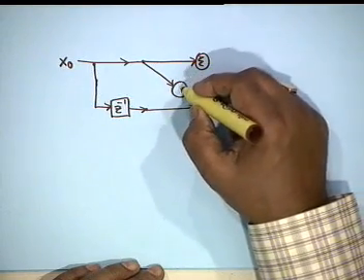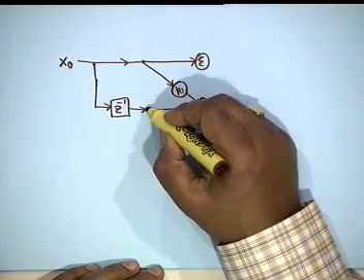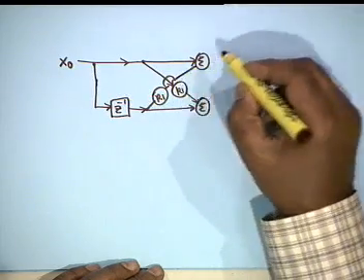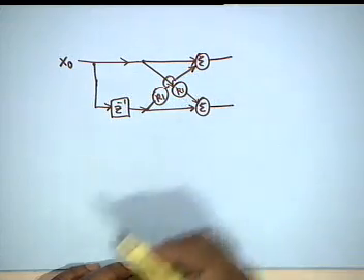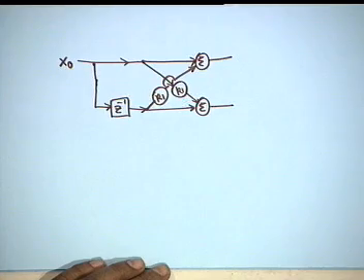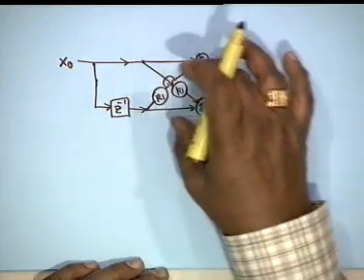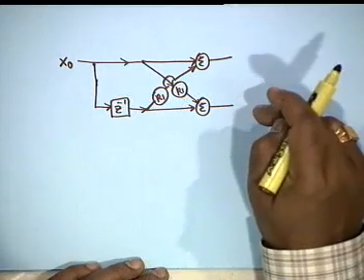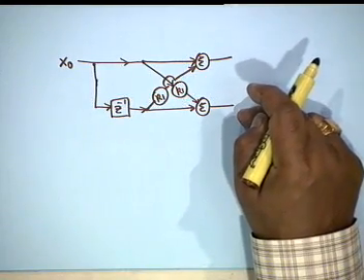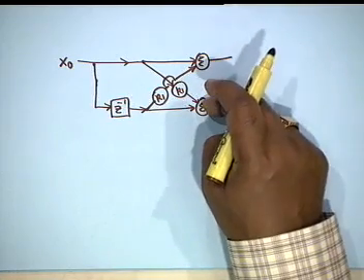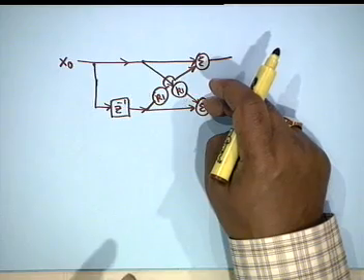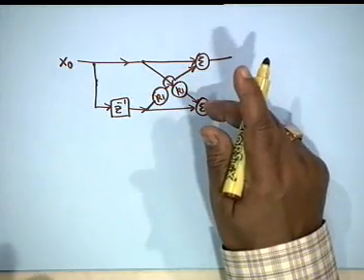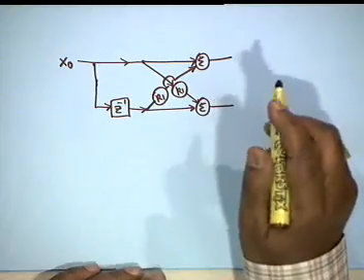This is K1 and this is also K1. This is the basic module. Okay? The basic module is that both lines go in the forward direction, the multipliers also go in the forward direction, but in a crisscross manner, and the difference between IIR lattice and FIR lattice is that the two multipliers are identical. Okay. This can also be realized by a single multiplier structure. It requires a little bit of innovation.